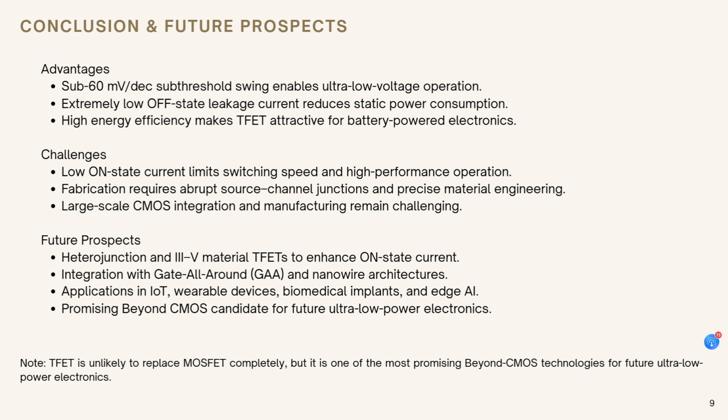Another important benefit is its extremely low off-state leakage current. Since current only flows through band-to-band tunneling, standby power consumption is greatly reduced. This makes TFETs particularly suitable for battery-powered and always-on electronic systems, where energy efficiency is a priority.